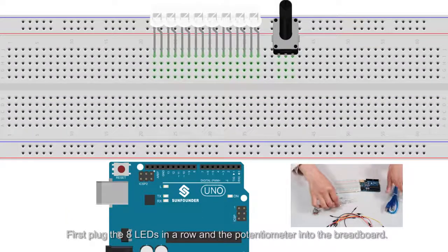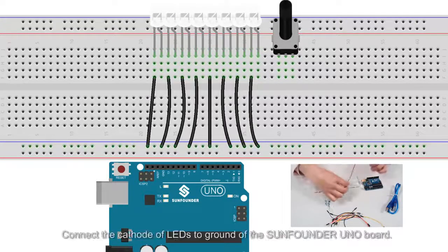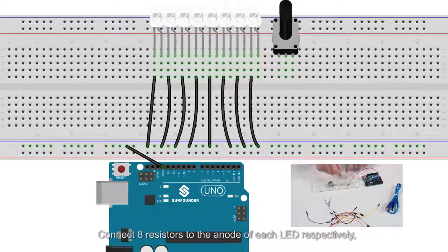First, plug the 8 LEDs in a row and the potentiometer into the breadboard. Connect the cathode of LEDs to ground of the SunFounder Uno board. Connect 8 resistors to the anode of each LED respectively.